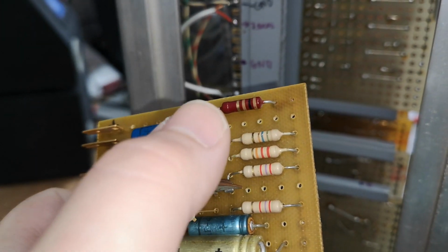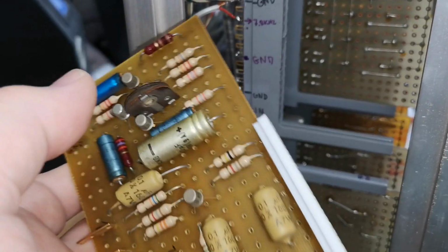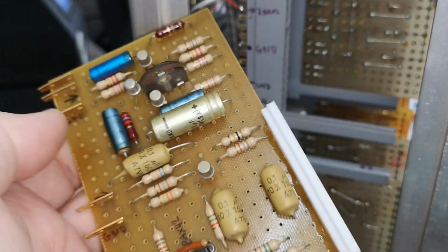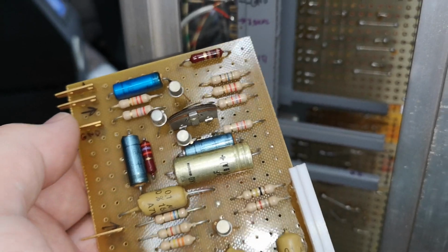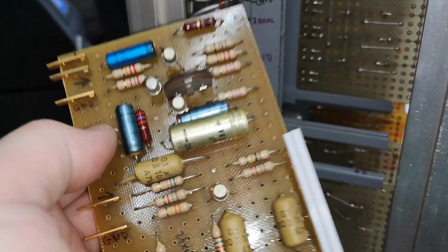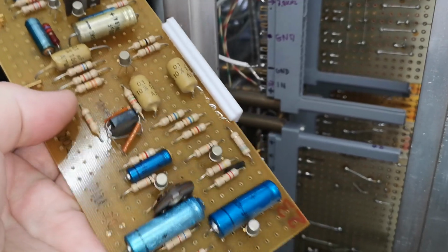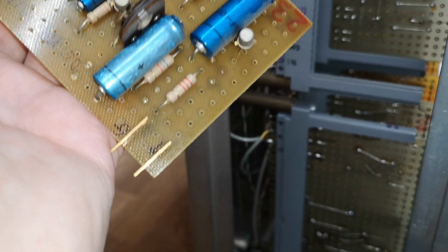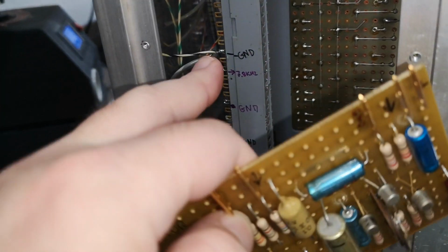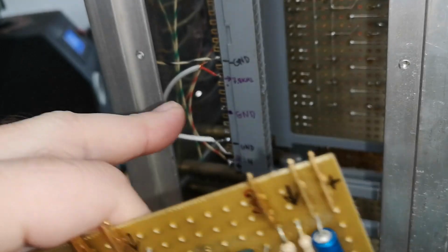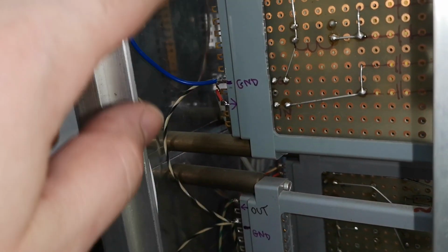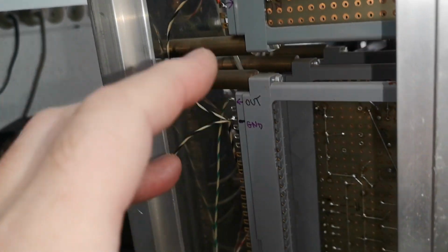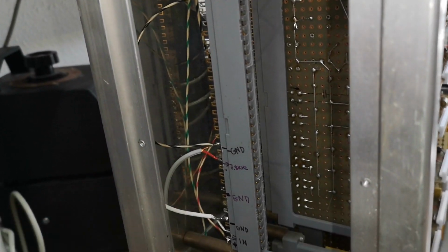Also, by adding series resistors to each board, that means now my power supply is not pulling AC currents. And when the power supply is not doing that, that means my ground is dead. So when I'm not pulling AC currents on the ground, then I can much more freely share the ground wires with other modules and this way interconnect in this kind of madness wire system that they're using back and forward with no returns and stuff like that.